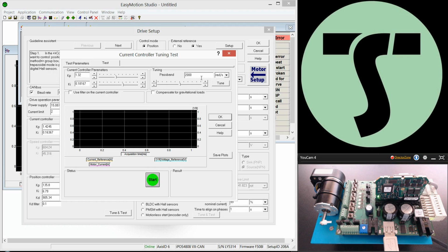The minimal way of explaining the passband is that the higher the value, the faster and sharper will be the controller response. In other words, the controller will be able to follow higher frequencies in the reference, therefore we can say that it has a high bandwidth or passband.